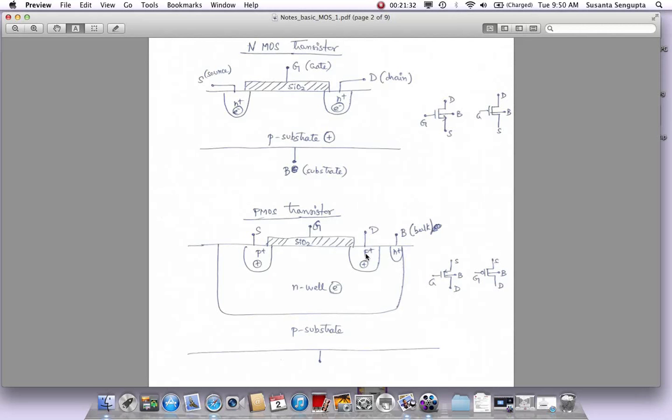So in a way, that's how the holes could move and cause conduction of current, because it's the electrons which are moving, which in a way is causing the holes to move in the opposite direction. So the direction the electrons move, holes are moving in the opposite direction. So even though the current is caused by the movement of electrons, it is defined more like by holes which are not physically moving. It's a little confusing, but always understand that holes are the places where it is devoid of electrons.